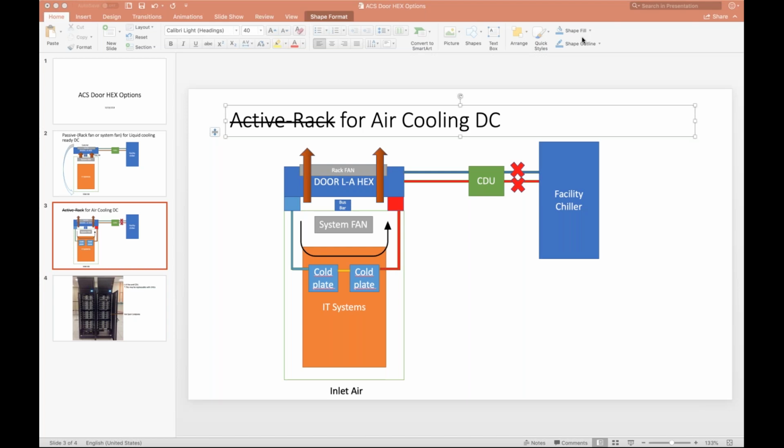One of the differences I can think of with the cold plate workstream, though I can't really represent what is defining the work of that workstream at this moment, is that it might be more defined with the facility water ready. And maybe they don't need a real heat exchanger type of solution, they might have a more liquid to liquid exchanger. While here we're using the liquid to air heat exchanger to cool the water for the second internal loop. Does that make sense?